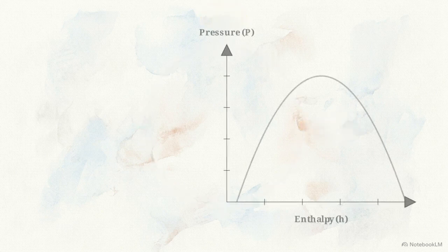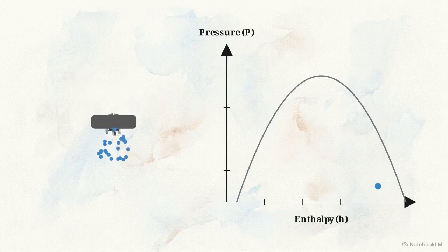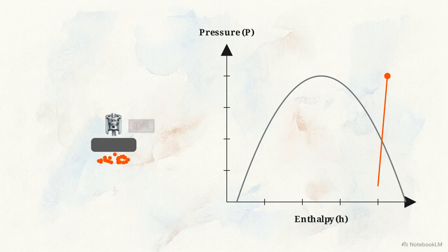To track how this cycle moves heat, look at the pressure enthalpy graph on the right. We'll plot the refrigerant state as it moves through the hardware on the left. We begin outside at the compressor. Low-pressure gas enters, plotted here at the bottom right. The compressor applies mechanical work to forcefully squeeze the R32, reducing its volume. This friction and compression cause the pressure and temperature to spike dramatically, shooting the fluid state straight up on our graph. By the time the gas exits the compressor, it has reached a scorching 70 to 80 degrees Celsius.